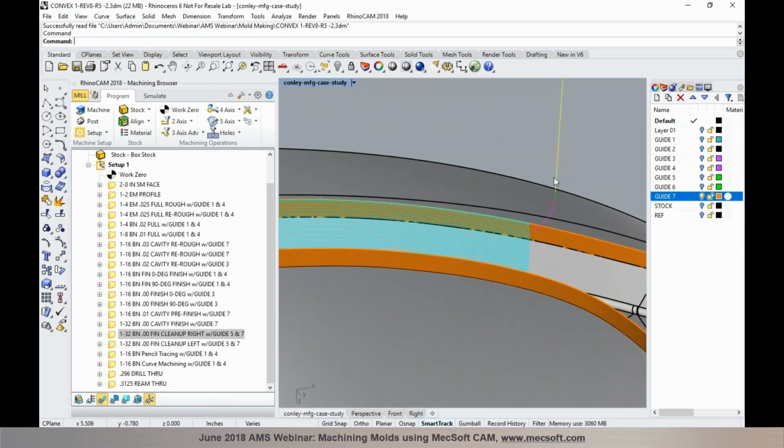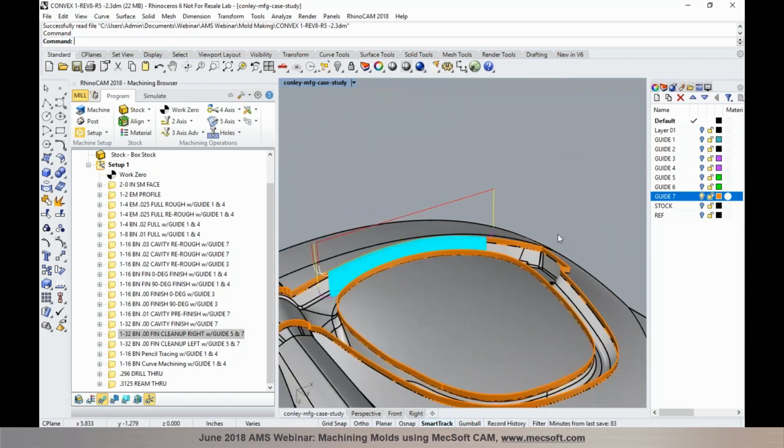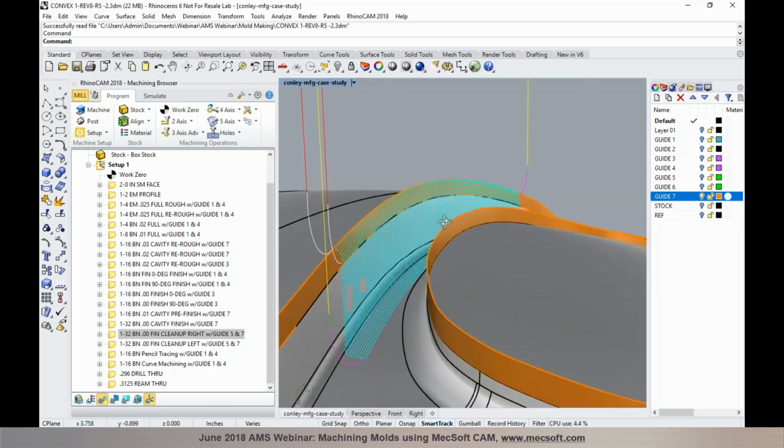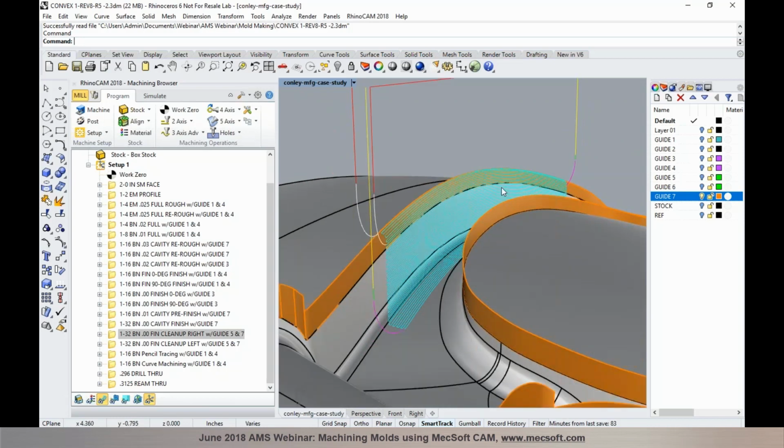So you have these controls where you can basically apply different feed rates for each of these motions, starting with your plunge, approach, engage, and then your cut motions. Now with these surface extensions that are being displayed in here, you will ensure that the parting edge remains sharp and the toolpath nicely flows into those extended surfaces. There was nothing additional you had to do in terms of generating the toolpath once you had those surfaces extended on the model itself.